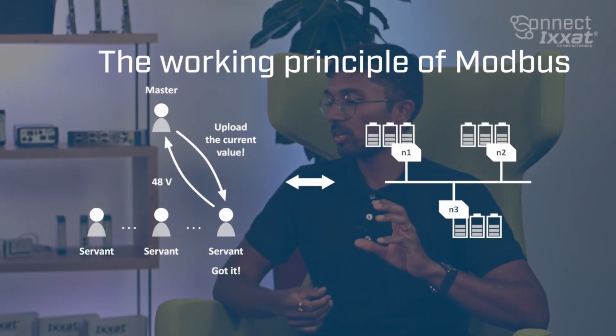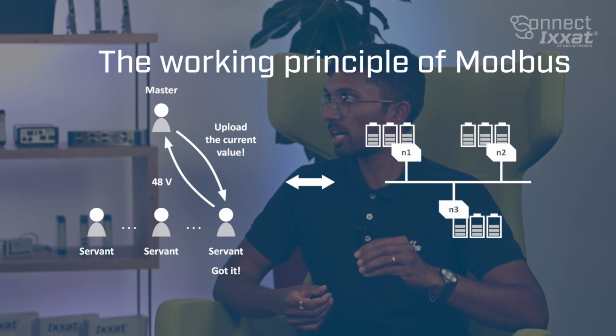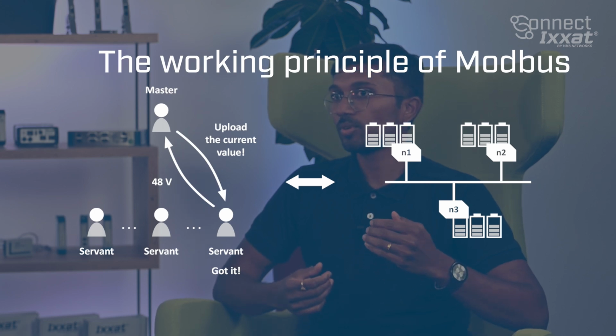The other alternative to CAN in the battery space is the Modbus protocol, and we see that Modbus is being adopted by many upcoming organizations in the battery space. But where we observe a clear differentiation is that these Modbus protocols are mostly suitable for small-scale installations, because Modbus usually has a polling mechanism, and when you talk about large-scale battery installations, CAN bus is your go-to technology.